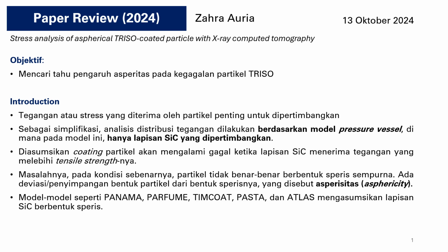In this paper, we want to know how the asphericity affects the failure of a coated TRISO particle. We know that the stress applied to the particle is important to consider because, from the simplification, the stress distribution analysis is done based on the pressure vessel model only, in which we only consider the silicon carbide layer.